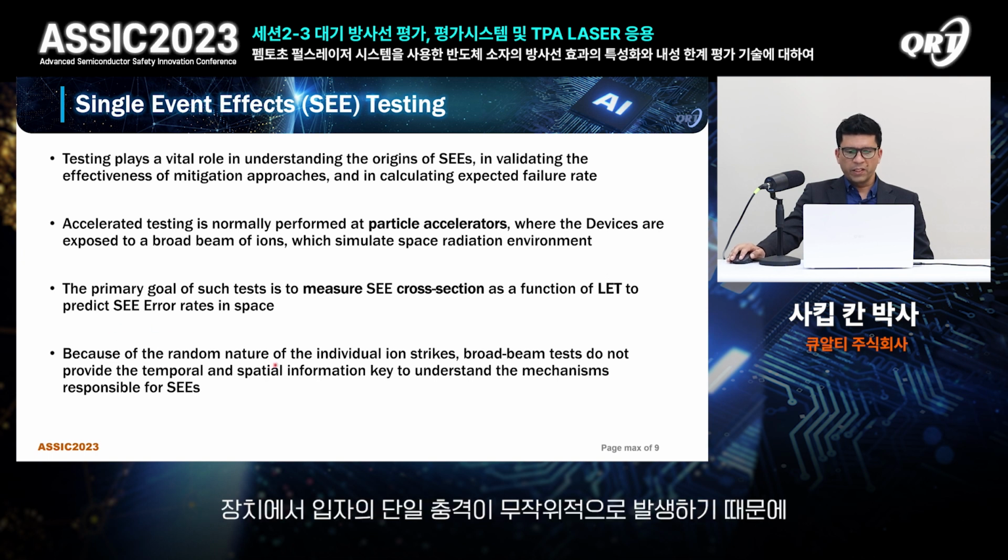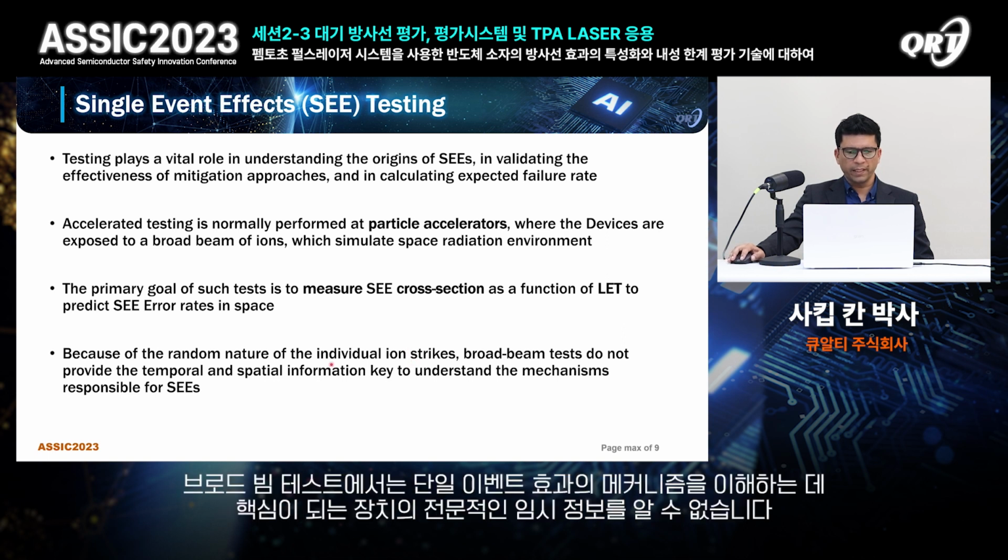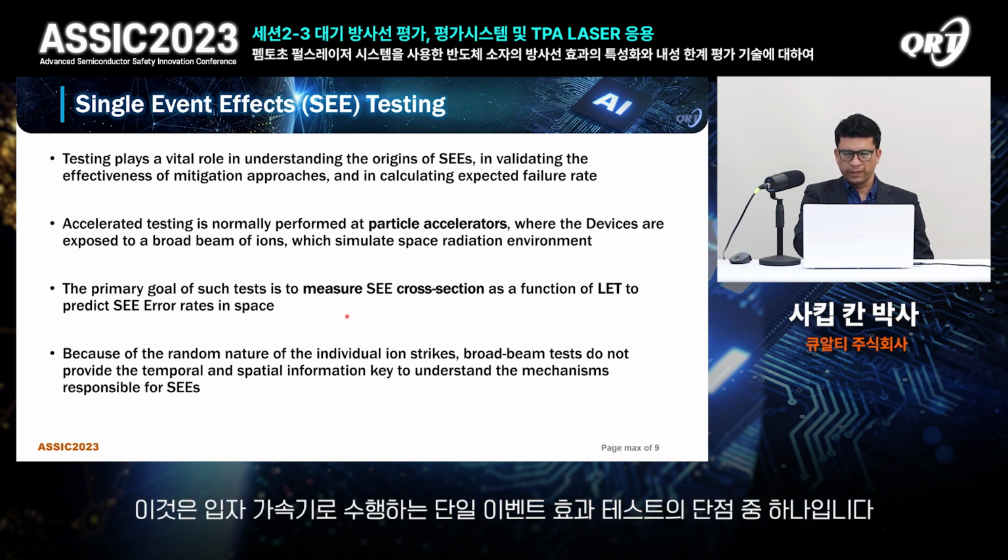Because of the random nature of the individual strike of the particle in the device, broad beam tests do not provide the temporal and the spatial information of the device, which are key to understand the mechanism behind the single event effect. So this is one of the downsides of single event effect testing using particle accelerators. Besides this,